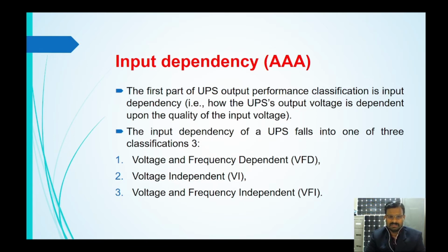Based on that, we can classify the input dependency of the UPS into three categories: the UPS which is voltage and frequency dependent, the UPS which is voltage independent, and the third one, voltage and frequency independent.